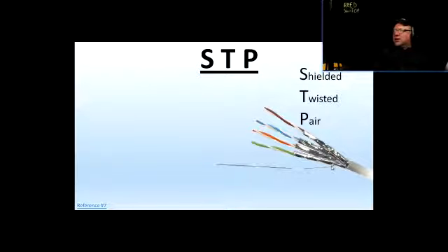Okay, and then it has something that's called a shield wire or a drain wire, and usually that would be connected to a ground terminal or a bond terminal. The difference between ground and bond is that they should have the same potential, but the grounded terminal goes straight to a ground spike driven into the ground, so true ground.